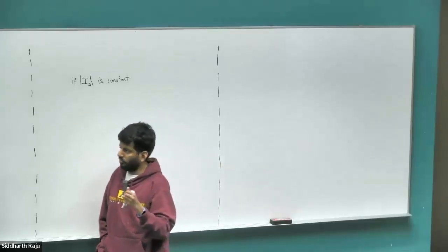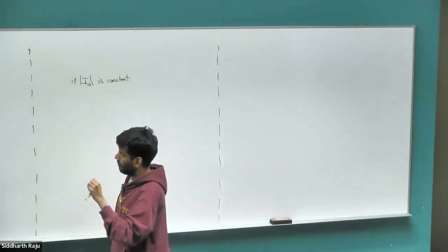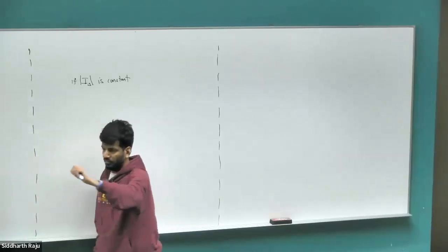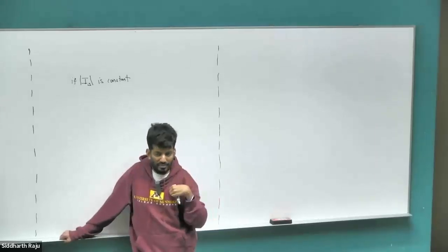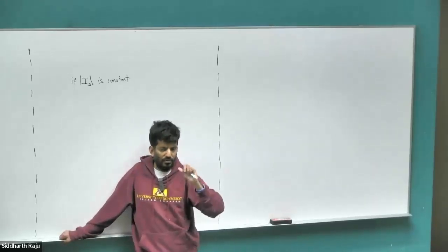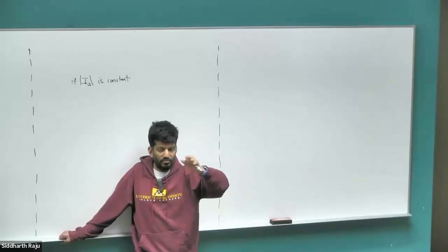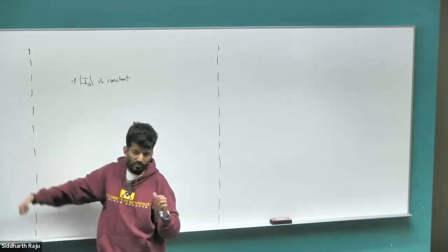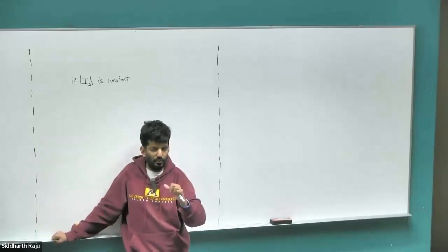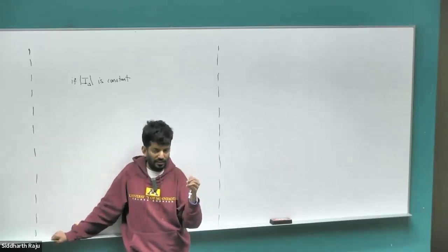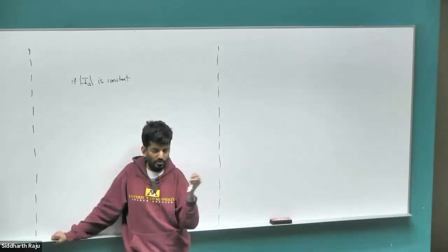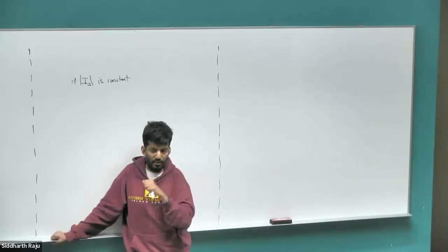So that's the idea: if you look at the space vector, these are all rotating at some speed, which is basically the synchronous speed. And instead of looking at it from a stationary reference frame, if you were to look at it from a rotational reference frame moving at the same speed as the space vector, all of these quantities are DC entities. So instead of controlling your actual stator currents, if you were to control the space vector that is created, then you have DC entities. You can create a PI controller just as you have done for a DC motor. It behaves exactly like a DC motor model. And then you can create your KP, KI values, design everything, control your space vector.